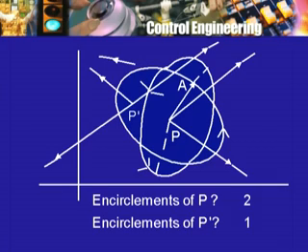In fact, you can copy this figure, put the point P dash, actually take your ruler, or as I have done it, use your finger or your ball pen or whatever, and literally trace the movement of the radius vector as you go around the curve, and ascertain for yourself that the net rotation as the point traverses around the curve is through 360 degrees, and therefore the number of encirclements is 1 and not 2 or 0 or minus 1 or whatever else.